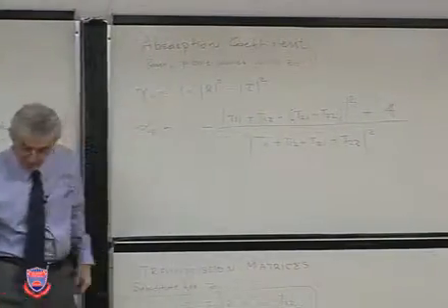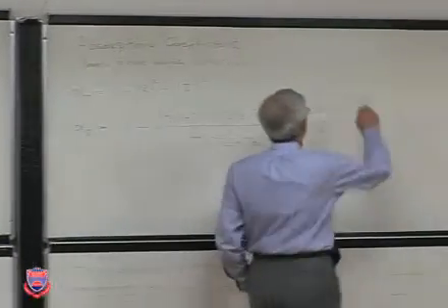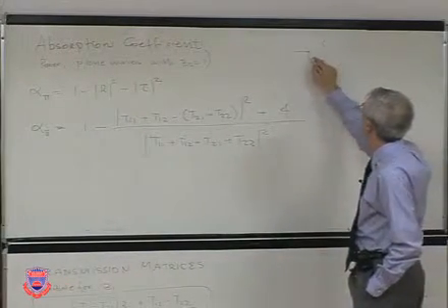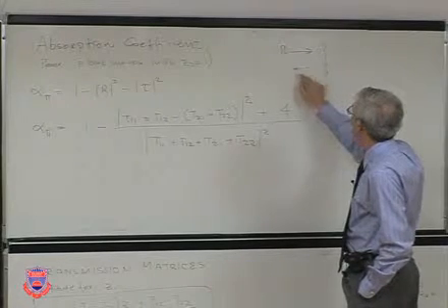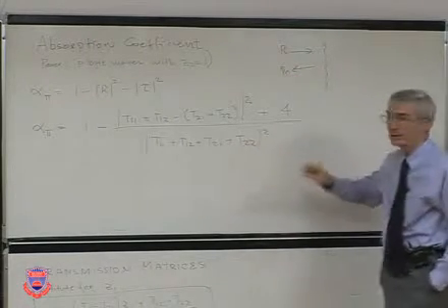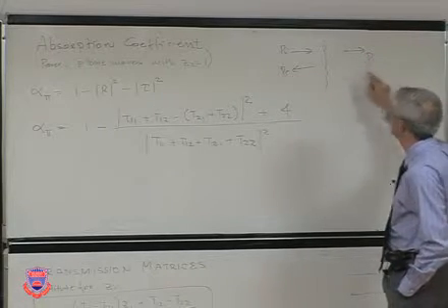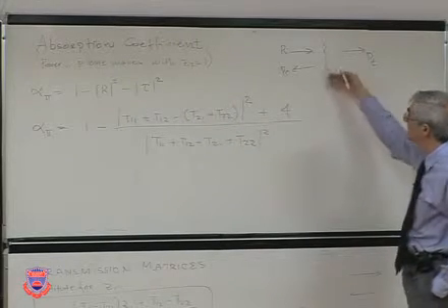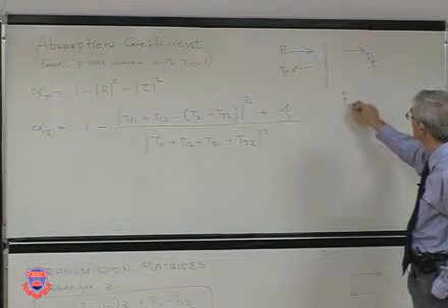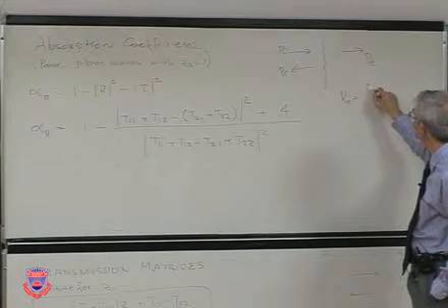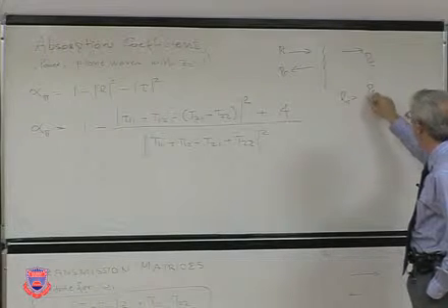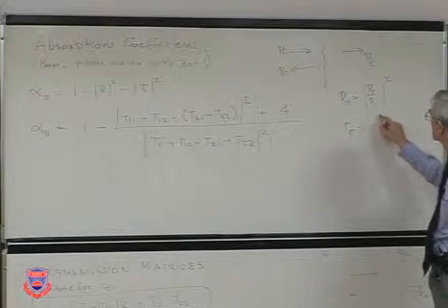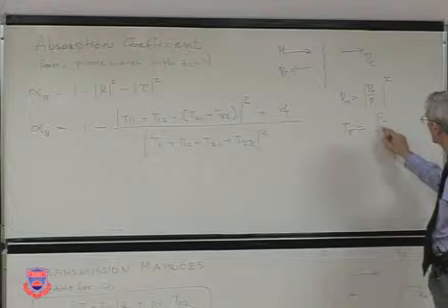Now, yes. How do we derive the absorption coefficient? This is when you have, let's say, a surface. Pressure is incident and some pressure is reflected and some pressure is transmitted. Now, if you consider these in terms of power, and normalize them with respect to it, so reflection is basically for plane waves, the power reflection coefficient. And the transmission coefficient is very similar to it.